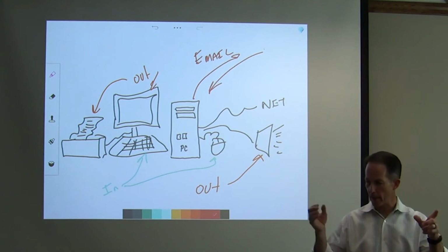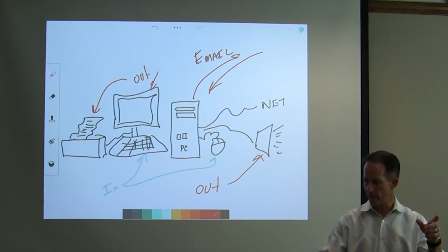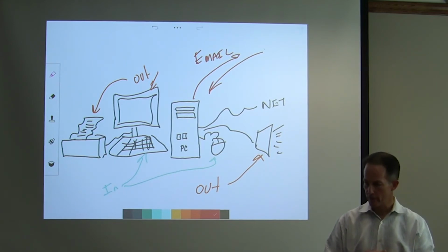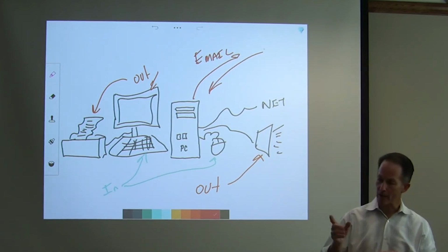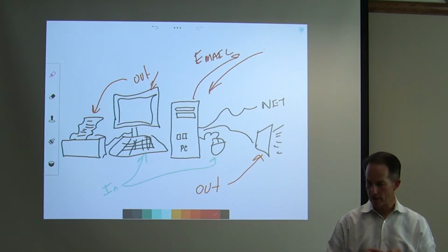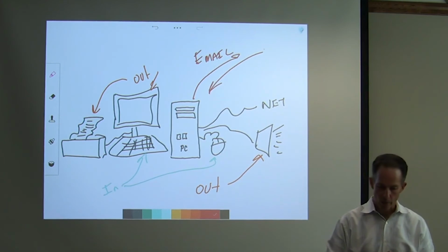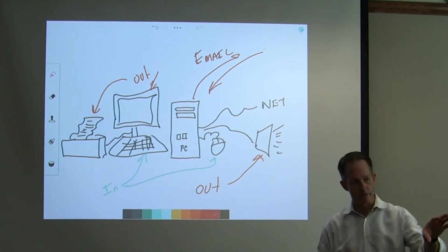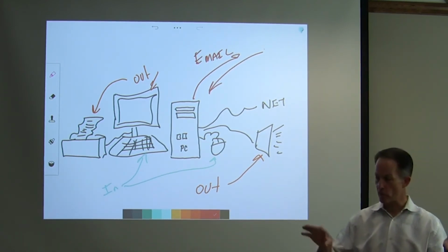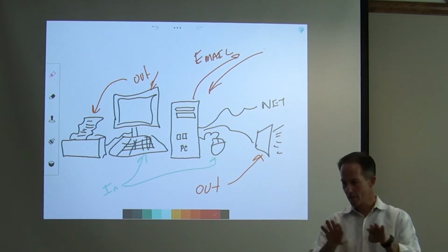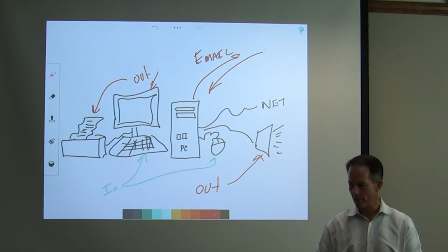Can Johnson and Delta or Distech, or will the JACEs talk Johnson? It all depends on the licensing. And the licensing will allow us to use certain protocols or not. And whether or not we can get licensing for Johnson on a JACE that is through Distech sometimes is not possible because they're competing providers, or manufacturers. But we can.